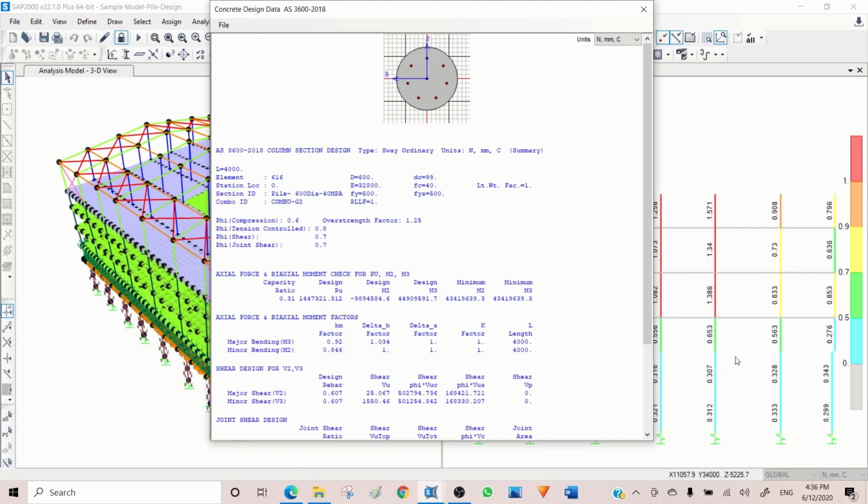If they are in loose sand, yet that's okay, but if they are in the rock, then you can reduce this length. And even for loose sand, it's not fully unsupported, so you can justify the unsupported length based on the stiffness of the soil. You may end up with 2 meters or 1.5 meters or anything like that. That could be mainly based on your engineering judgment. I wouldn't say there is a specific formula to reduce the length of the pile when it's confined in rock or sand, but based on the stiffness you can make a decision.